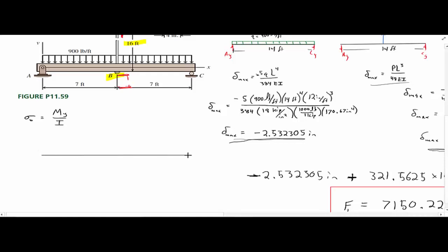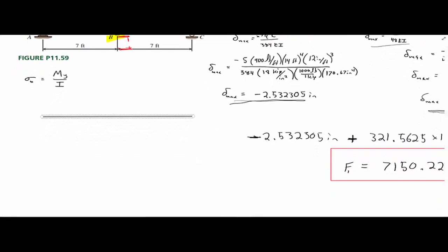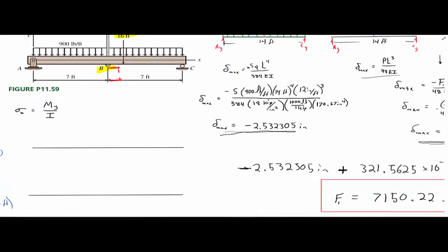So to be able to solve that, let's just go back to what we learned in statics. We're going to draw our shear and moment diagrams. That's our shear, and this is moment. Shear will be in pounds, and moment will be pound-feet. Solving for our reactions, which you could do through statics because now you know your forces, you can just draw a free body diagram of this section, this assembly, and then solve for your exterior reactions.